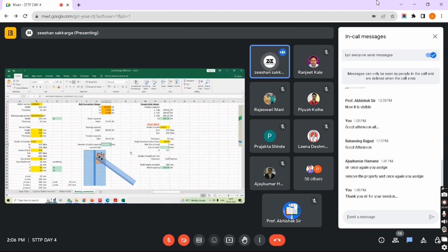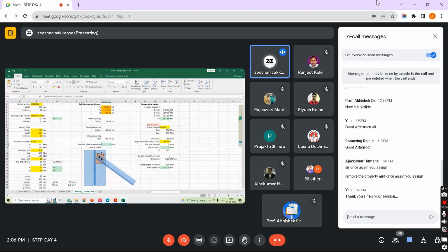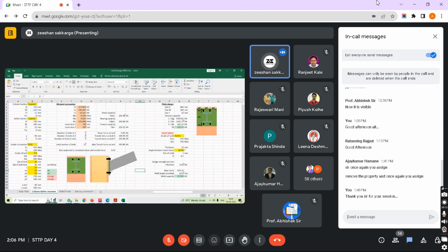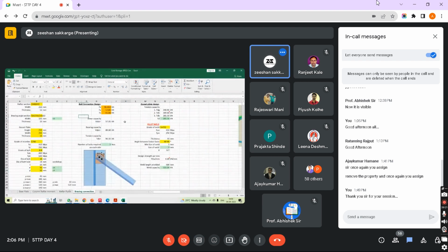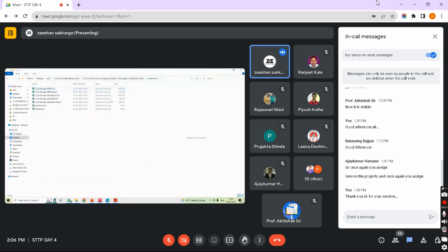Right now I require 2 bolts. Here it will check the welding. Welding is also fine. Okay, so these are the things which we should check for the base plate. If I enter my requirements, I will get the utilization and the number of bolts required. Yeah, we have similarly for the column and rafter connections. These are some of the Excels which we use for the purlin connections. Okay, I will just close them. Don't save. I already have it.